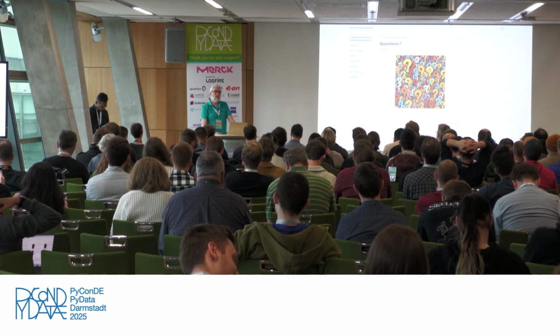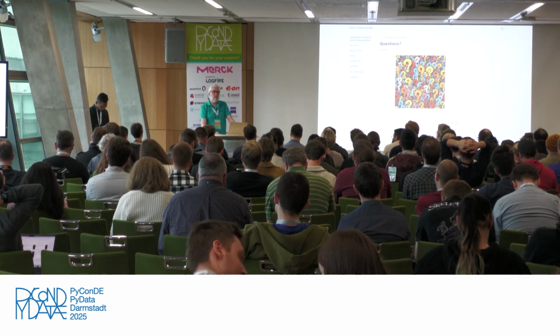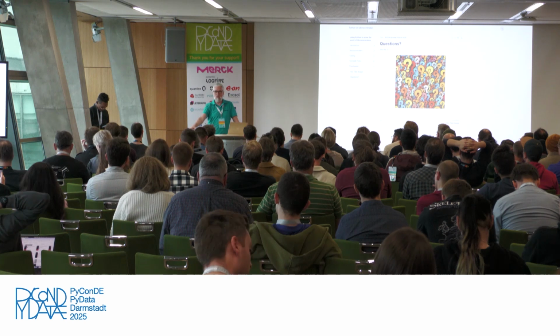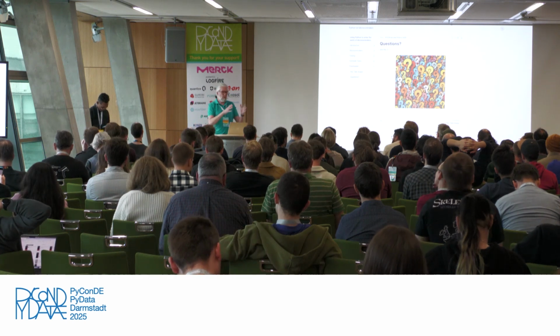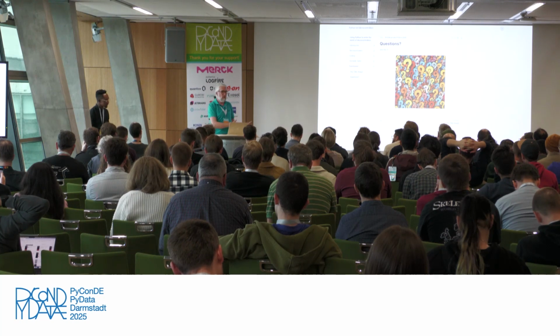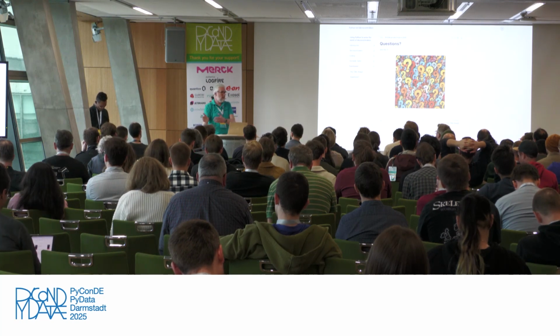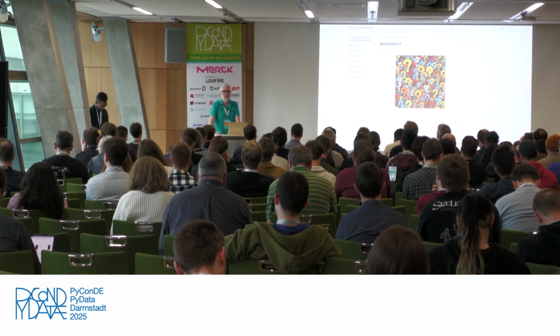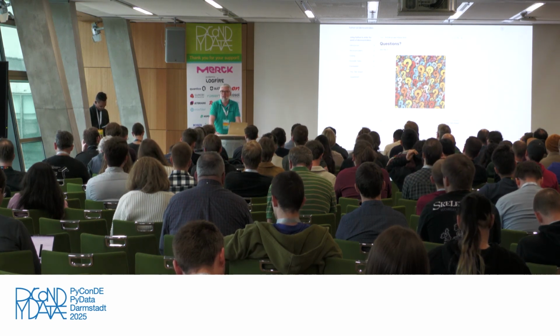And then there is another tool called mpremote, and that is your bridge from your computer to that very microcontroller. You can mount your local file system on the microcontroller, so you don't even have to transfer all the libraries for the development cycle to that microcontroller. Just use it and play around with it. That is a fantastic world to play interactively and develop.